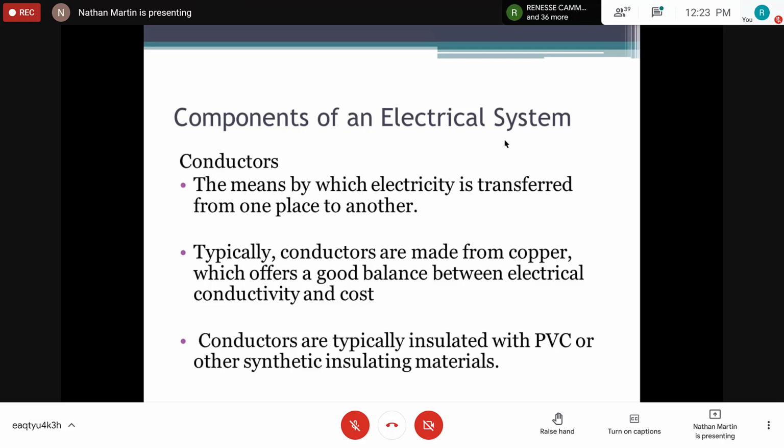It's designed for that purpose, right? The temperature rating for this type of cable is approximately 90 degrees, right? So for those triplex cables that you see everybody using, the insulation type is really the XHHW type, which is actually designed for that particular type of use.